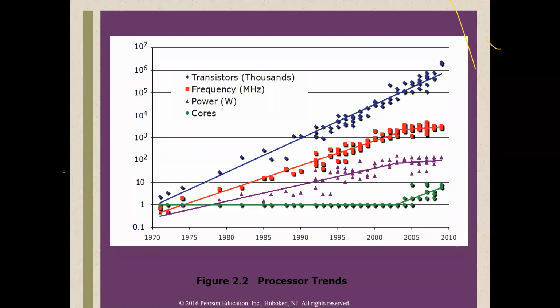And so contemporary chips devote over half of the chip area to caches now, because instead of the very first Pentium that had only level 1, now it has level 1 and 2 on board the processor chip. And not only that, it is also split into instruction and data: instruction level 2, instruction level, data level 2. So it means it requires more space.